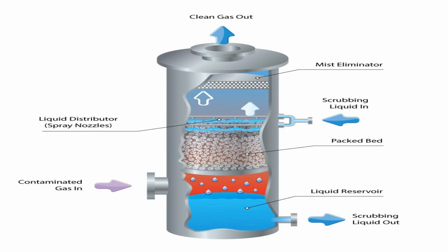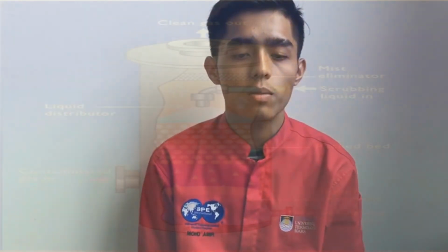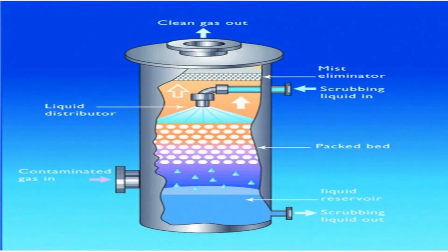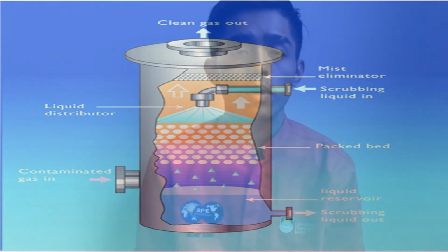The most commonly used application in oil and gas is gas absorption. Gas absorption, also known as scrubbing, is an operation in which a gas mixture is contacted with a liquid for the purpose of preferentially dissolving one or more components of the gas mixture and to provide a solution of them in the liquid. Therefore, there is a mass transfer of the component of the gas from the gas phase to the liquid phase. The solute is said to be absorbed by the liquid.